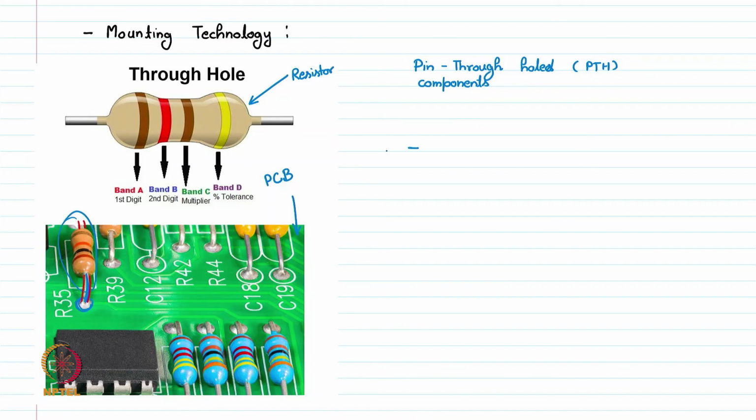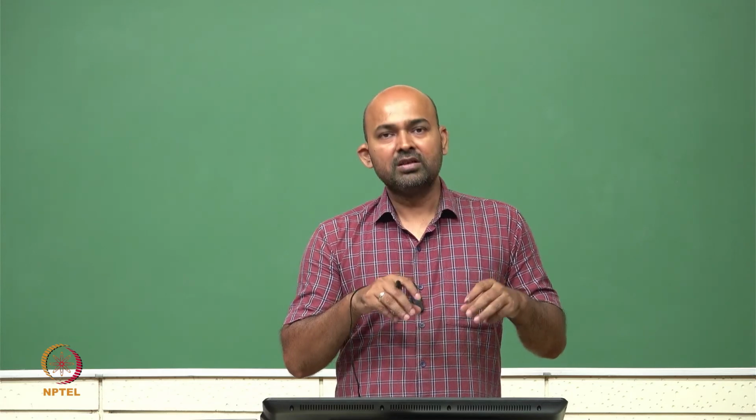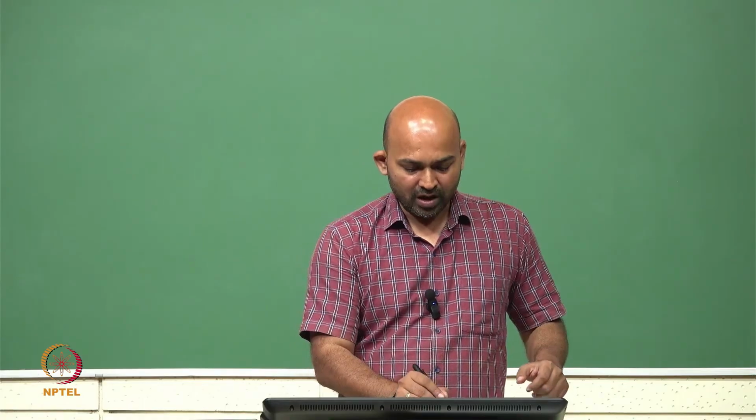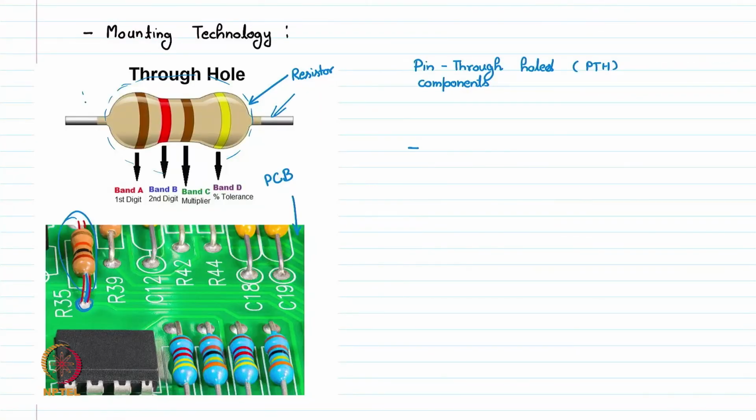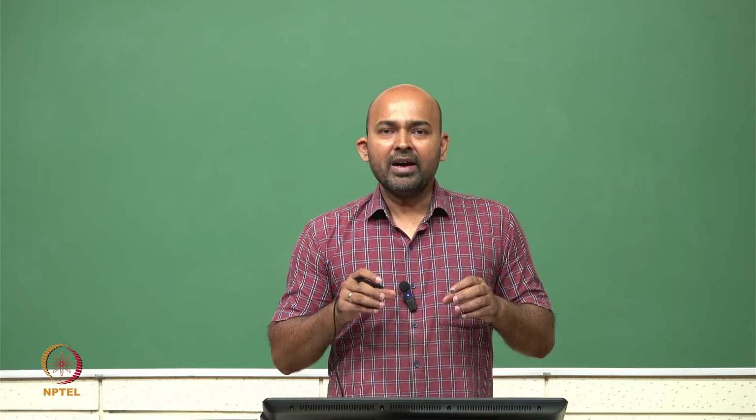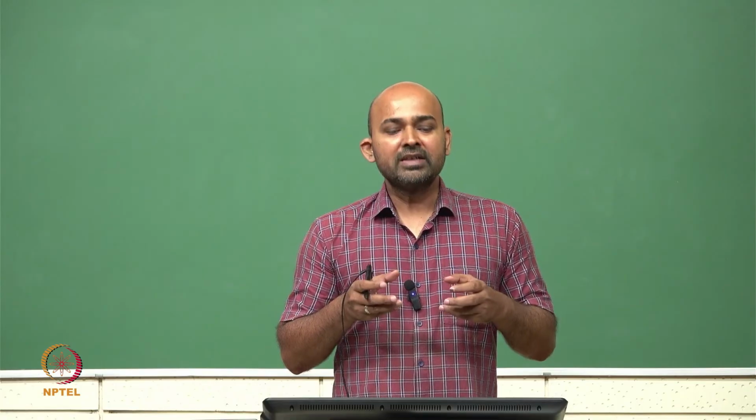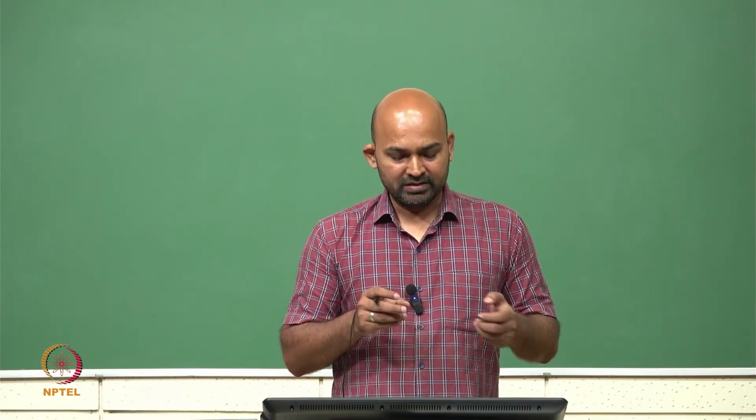The problem with this type of technology, where we have this PTH resistance, is these lead wires which are coming out from this component. The actual resistance is this brown color thing in this bead. To connect this resistance to the external circuit, we use these two arms, these metallic wires that come out. These bond wires actually contribute to parasitic inductance and capacitance.